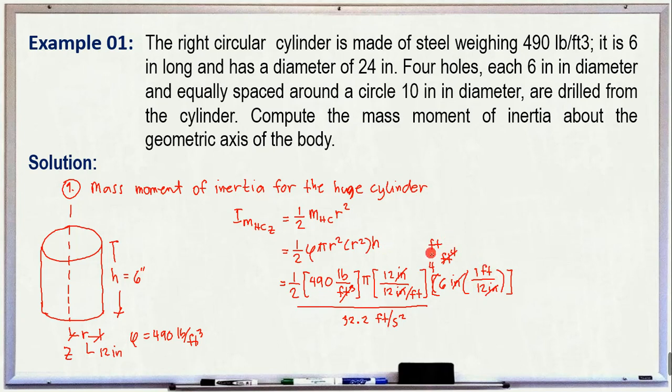So, we have 2 foot. So, cancel the one at the bottom. So, we have pound foot. Then, the second squared will be transferred to the numerator. So, it becomes pound foot second squared. So, we have achieved the desired dimension.